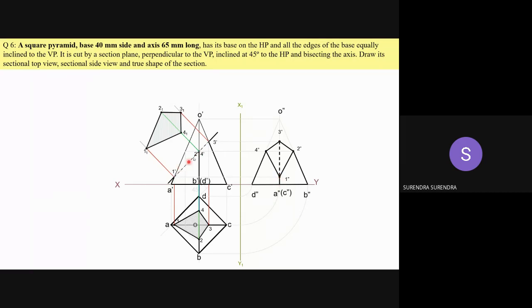But as we have removed the solid here, we have to represent the C3 edge up to this point as a dashed line and complete it with hatching. Is it clear?